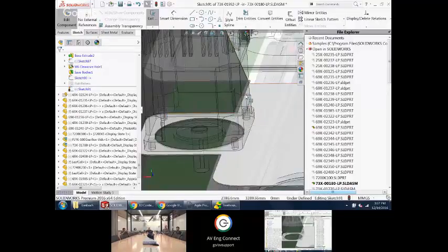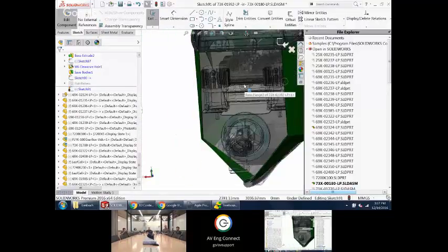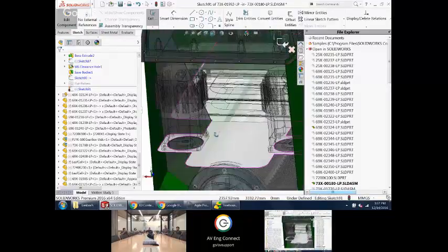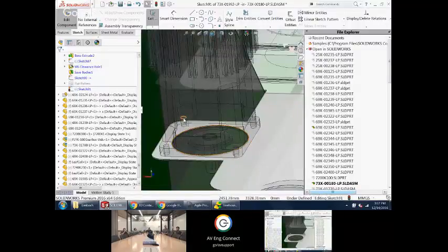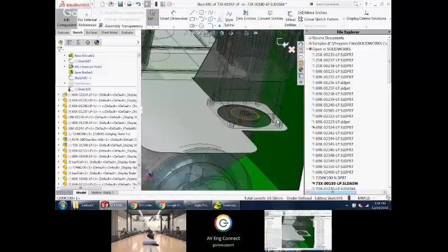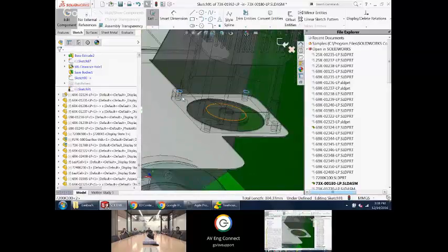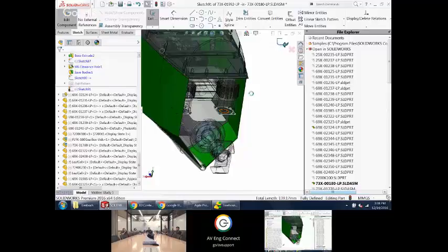Now, it does get tough for me to pick things when you are looking at this wireframe of the rest of the world. That's where those filters come in. If I press the letter E, that'll filter edges. And that gives me the ability to go through all of these faces really quickly as far as grabbing the edges from these motor mounts and then converting them down onto the sketch that I was working on before.